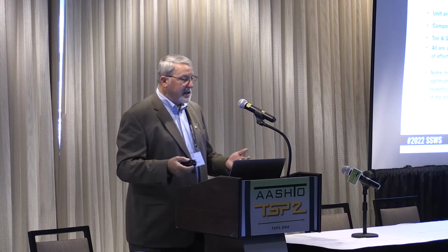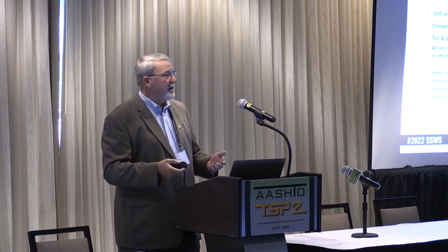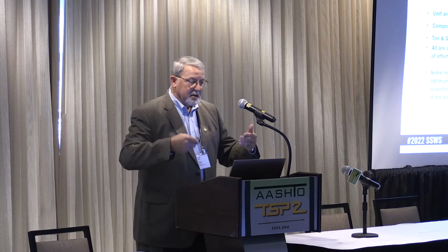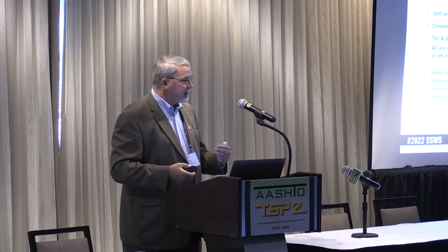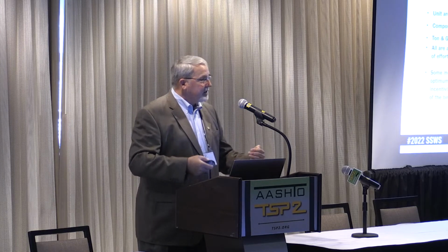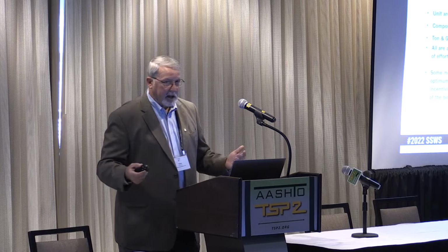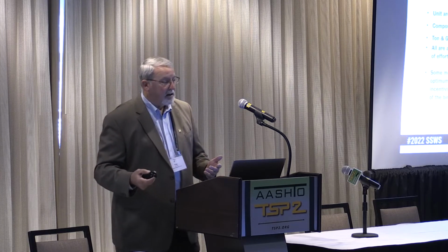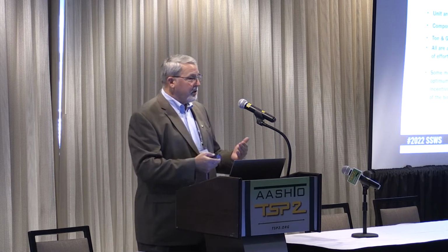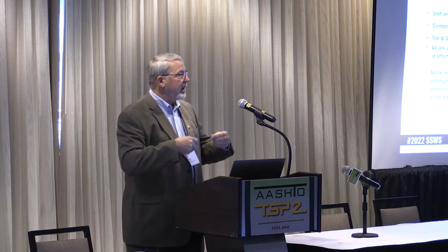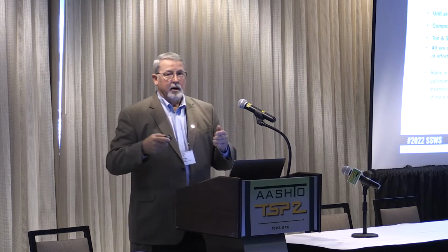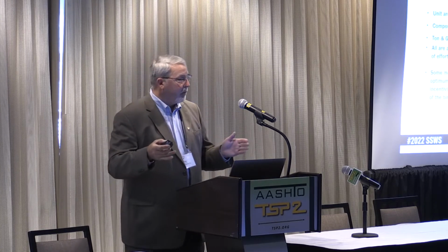And to an agency, they know when they bid a square yard job, if it's 100,000 square yards at $3 a square yard, they know exactly what their cost exposure is going to be. On bid day, it's going to be exactly what that cost exposure is at the end of the project. No changes. A lot of agencies like that. But when you do that, you have to go back to your application rates, job mix formula, and make sure that the applicators are operating within those windows set forth, and do it that way.